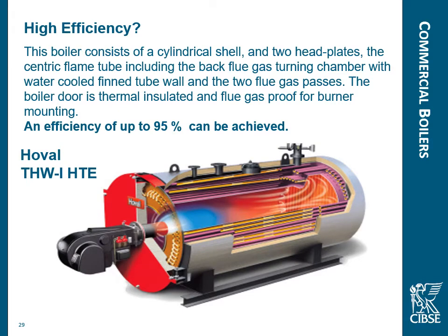Now, one of the latest boilers out there is this high efficiency boiler. Efficiency up to 95% can be achieved. But even that is still not really efficient enough if we're looking to move towards being carbon neutral by 2050. Even putting that into a new build now, we struggle to make the building comply with building regulations because of only the 95% efficiency. So if that boiler there is not good enough, what sort of efficiency are we looking at?